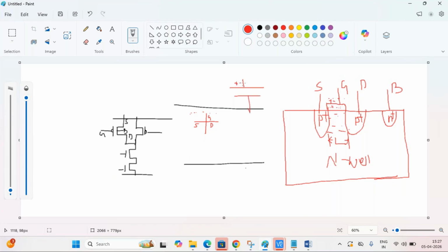Like a magnet attracts the opposite pole, negative charge deposits on one side, and similarly when you apply negative voltage, positive charge deposits. That positive charge creates a channel. From source to drain, current starts to flow as per your potential difference. So at 0, PMOS will be on. This is the cross-sectional view.